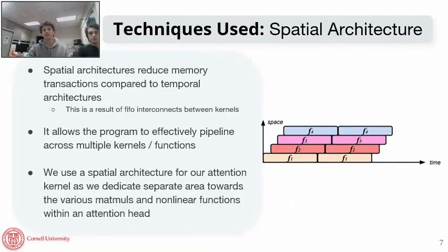One of the most powerful techniques we used was actually inspired by a paper written by Professor Zhang and his research group called Understanding the Potential of FPGA-Based Spatial Acceleration for Large Language Inference. In that paper, they discussed the benefit of using spatial architectures, where instead of having a temporal architecture where every function does very parallelized and fast processing, writes the data back to memory, and then reads it again, we create a dataflow where every single independent kernel is laid out in a spatial format, hence the name, and then is streamed via FIFOs. This seriously reduces memory accesses and allows for immense speedup.